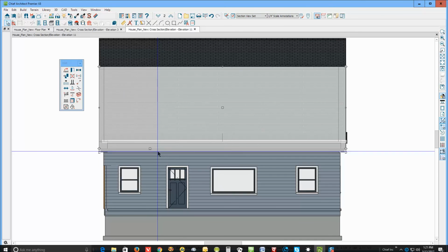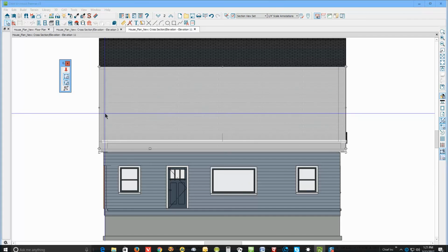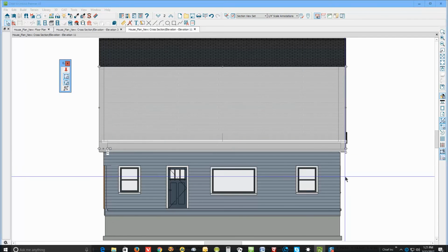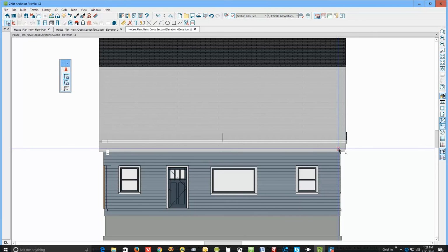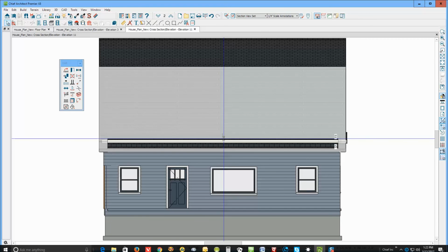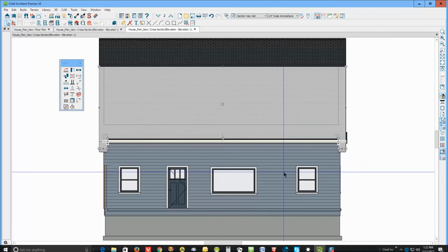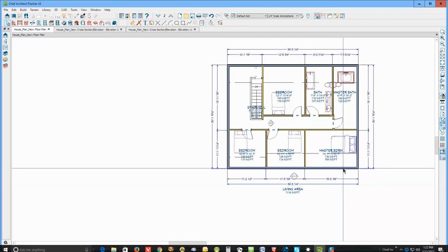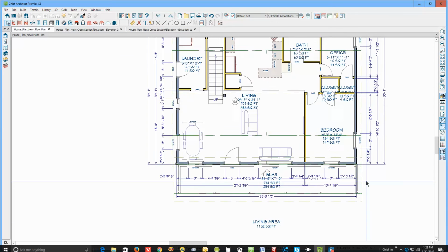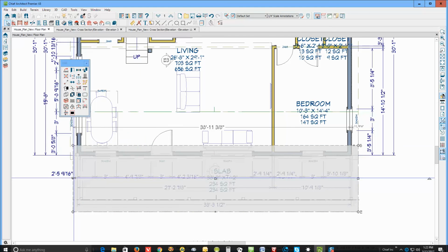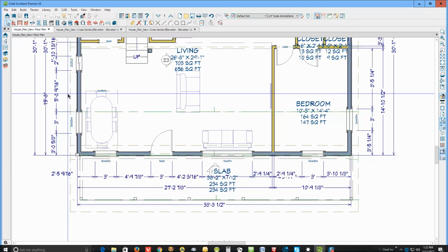Now, in the other model that you showed me, I'm going to use the break line tool and notch out the roofs on either end. Put a break here. We'll just rough this in, and then I can raise this up like that, and the software will fill in this area and leave the roof hanging down. Now I want to fix the roofs again. I just noticed that this end doesn't match the upper roofs, and they need to match in terms of the overhang. I don't care what you set it to, but they should match.